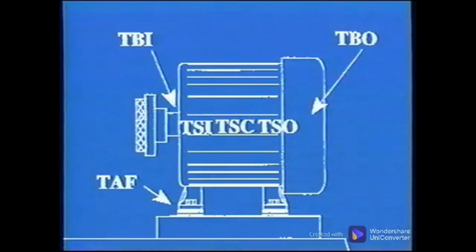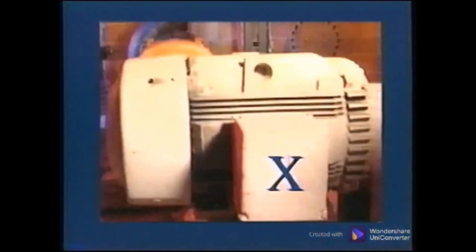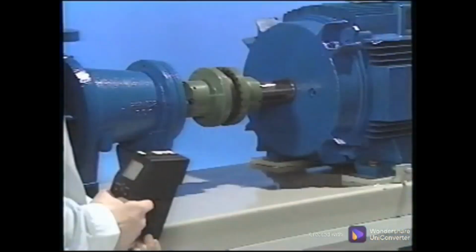Temperature measurements should be acquired when the motor is in a steady state condition. CSI recommends 7 locations for these measurements. 3 are surface or skin temperatures, plus 1 on each bearing, 1 at the center of the termination box, and 1 at the hottest spot on the coupling.